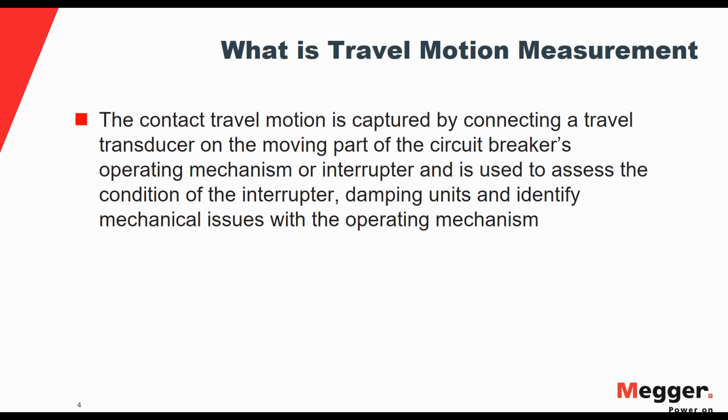Usually in your circuit breaker, you will have interrupters inside an insulating media like SF6, or in the old days you had oil, minimum oil or bulk oil, and also there is the air blast type circuit breaker, and in the medium voltage more commonly you find vacuum circuit breakers as well.